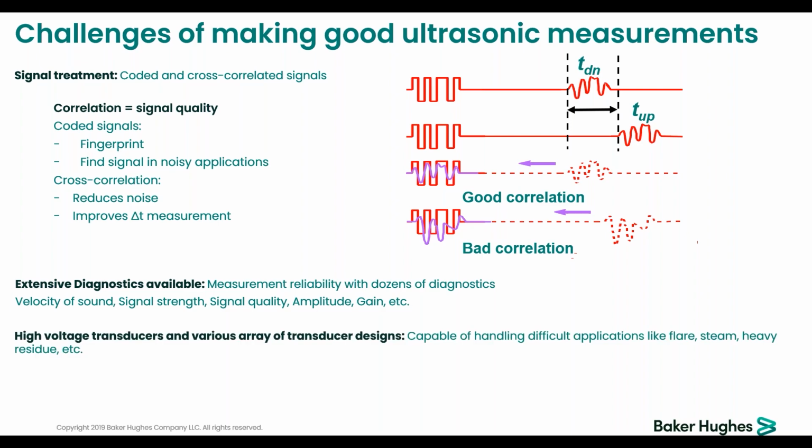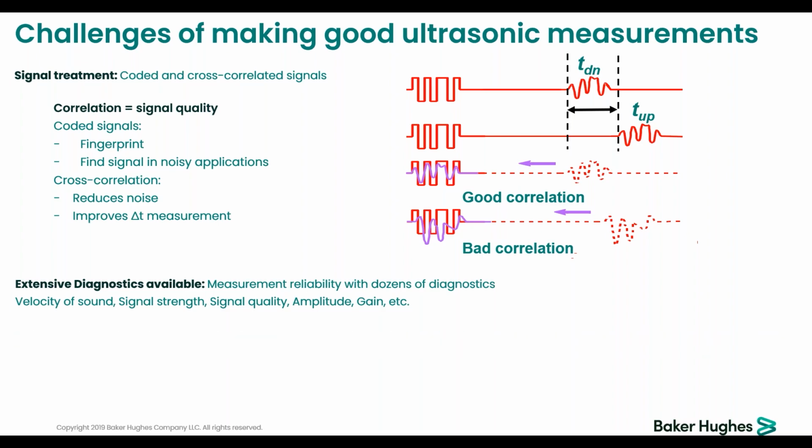The first one that you need to look at will be the velocity of sound, because if this one matches the theoretical one that is available from different literature as well as in our documents, then you get this correct and you can start looking at the other ones. If the velocity of sound that you get is not within 1 or 2% at max from the theoretical value, then you need to understand why, because it's probably not wise to look at the other diagnostics once this one is not properly addressed. Okay.